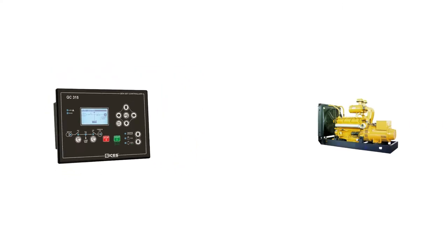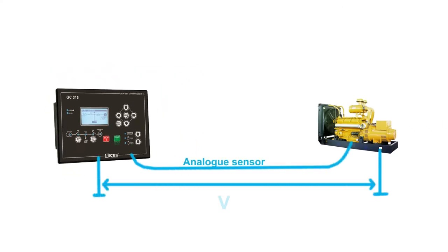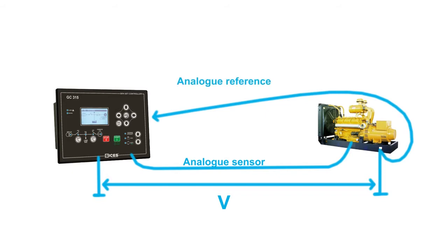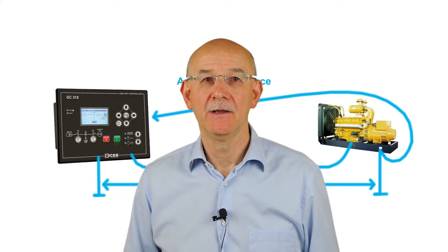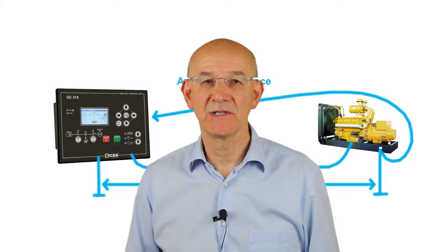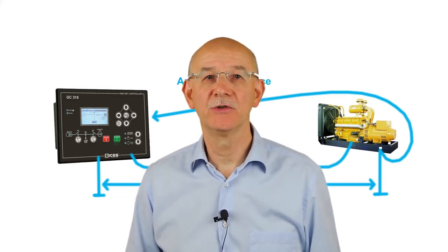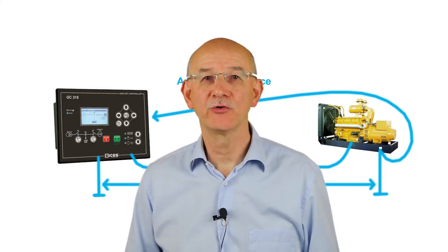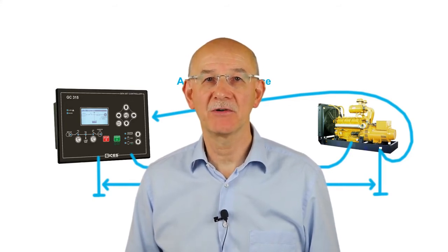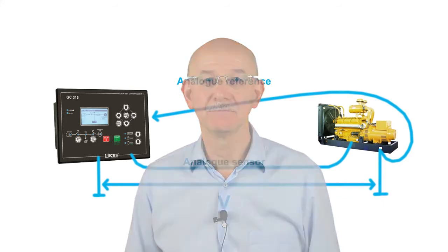Depending on the connection, steady or transitory voltage can develop across the engine and the controller ground. Usually, sensors are cabled only by one wire, and this voltage can influence the resistance measurement. It is not mandatory to use this input. In this case, a good ground wiring system or two-wire sensor cabling should be provided. If not used, JM1 must be connected to ground.